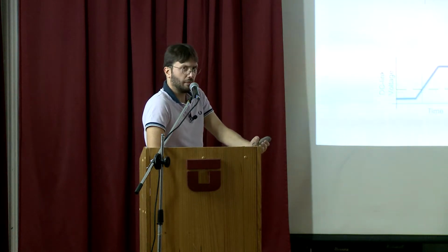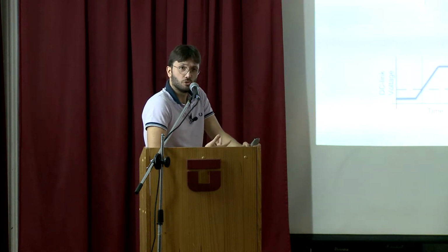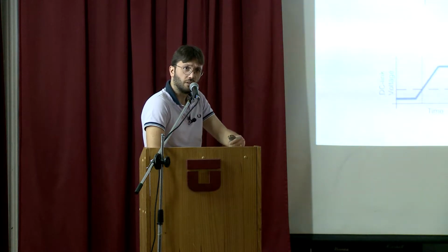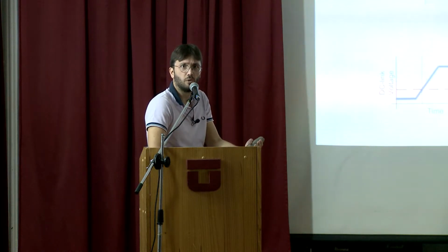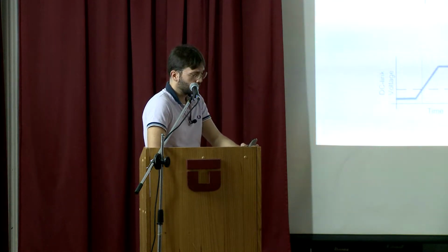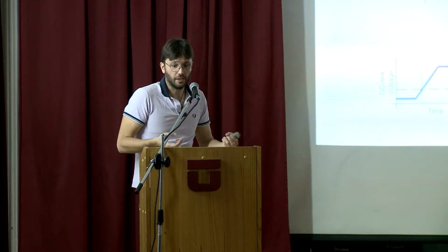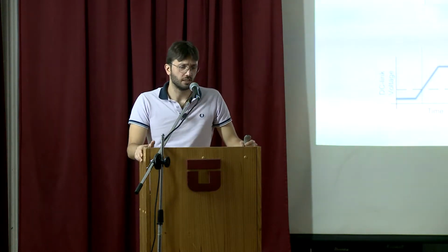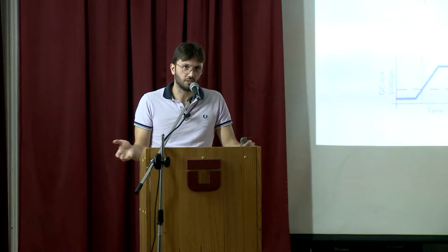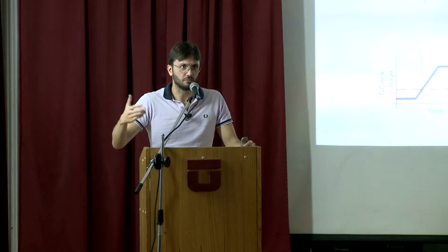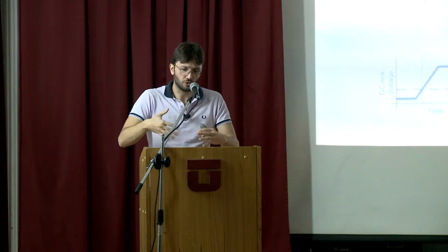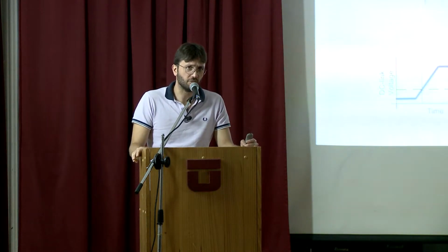So it basically means that there is some droop characteristic: when the frequency increases, the power is reduced proportionally. And this is basically in every PV power converter that is sold in Italy and maybe in Europe, because they all have the same firmware, I think.